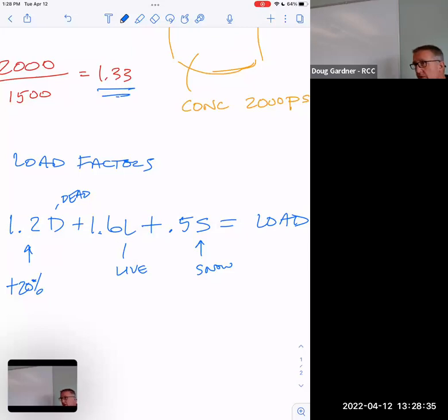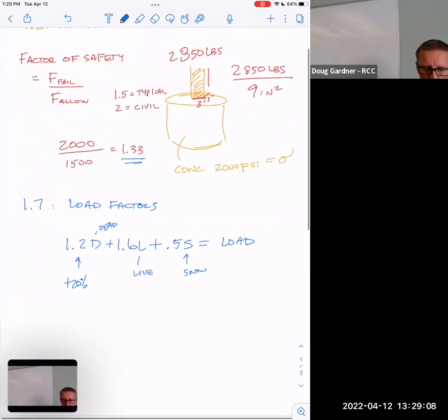As just a designer, I don't feel the freedom to make those kinds of decisions. But the engineers, a lot of times when I call them and we're making some decision about some footing, and I love picking their brain just because I understand enough of what they're doing that I can actually learn stuff from it. They a lot of times will have a far smaller load on something than I do, because I'm using just a generic load that's always used for roofs. And they're like, oh, in this case, you can actually just use 7 pounds a foot. I don't feel the freedom to do that. But this is kind of where it comes from. So anyway, I want you to understand that.